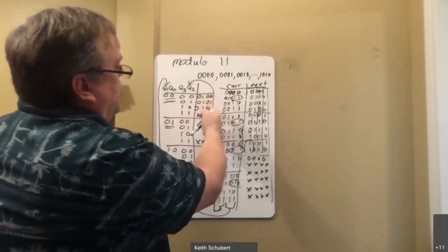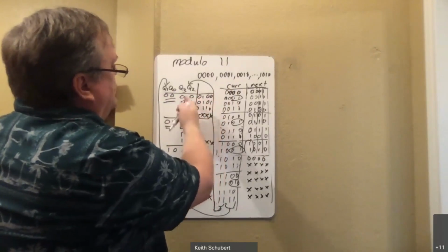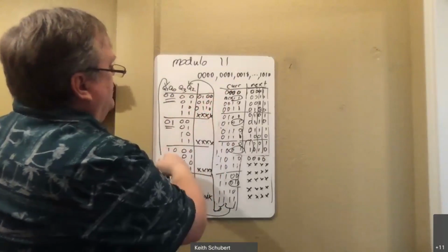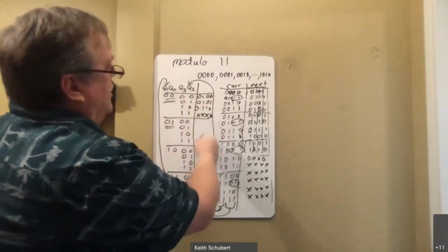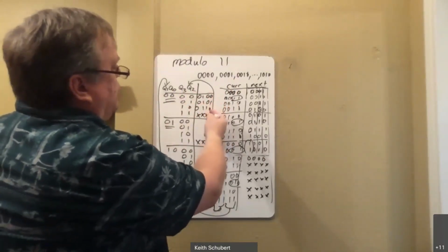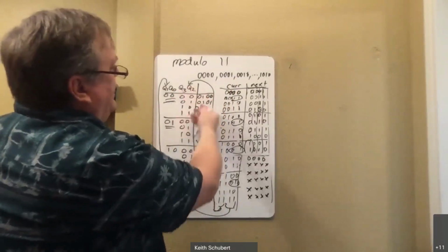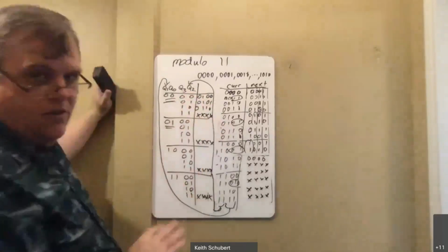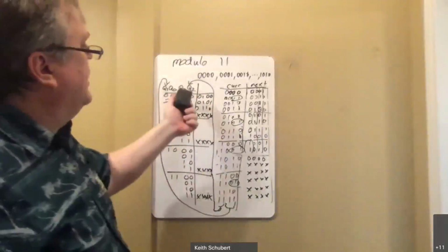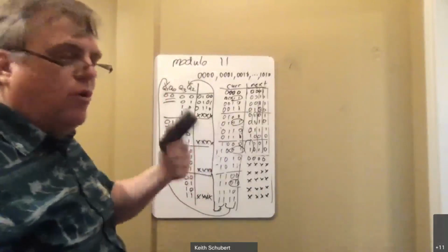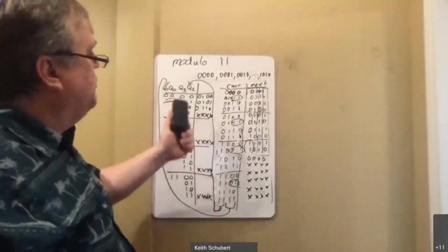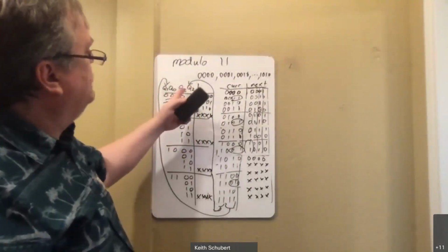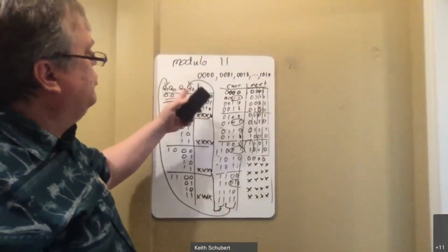0, 0, 1, something. Is there something over here that I haven't used that looks like 0, 0, 1, something? Right? 0, 1, 0, something. Anything here that looks like 0, 1, 0, something. Right? You ought to be able to figure out inputs I can put from Q3, Q2, 0, and 1, and possibly their primes. Right? And so you've got 2 NOT gates which allow you to deal with Q2 and Q3.